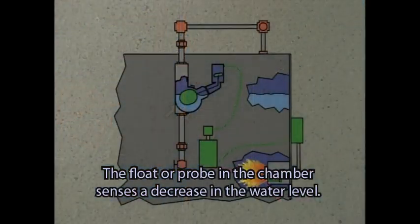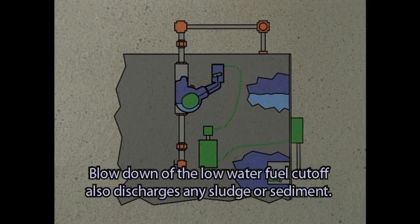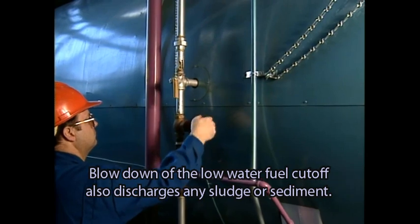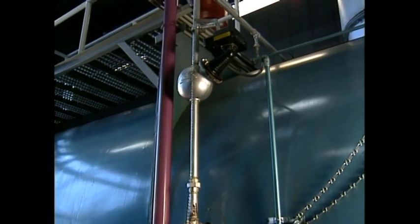The float or probe in the chamber senses a decrease in the water level. This simulates a loss of water in the boiler and shuts off fuel to the burner. Blowdown of the low water fuel cutoff also discharges any sludge or sediment. A reset switch is activated to restart the flow of fuel to the burner.